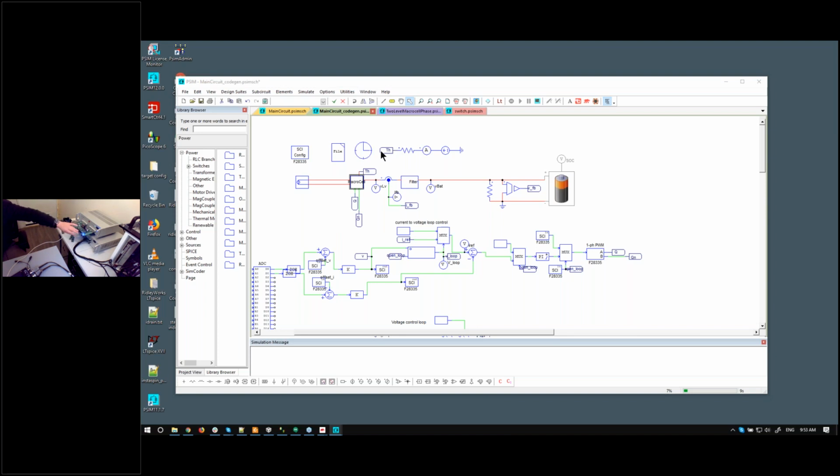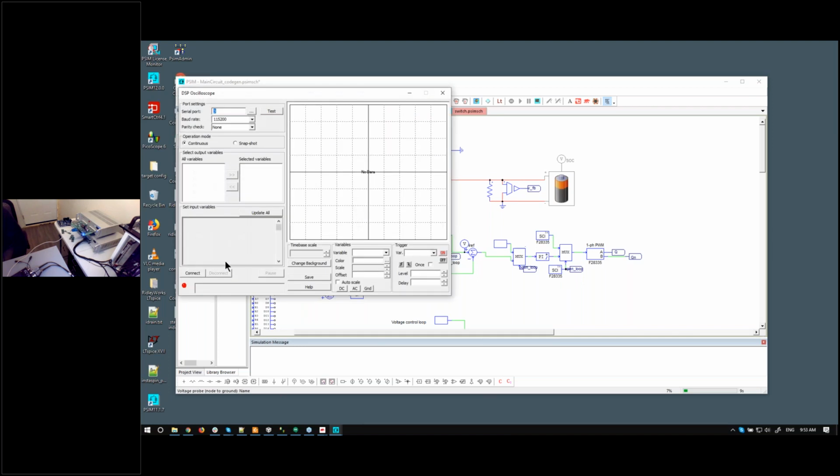So now over this cable here, I'm going to connect to the processor over serial communication. And what I'm going to be able to do is control, if you see in the schematic here, I've set up points where I can control things. So I'm going to be able to toggle this between open loop and closed loop, and I'm going to be able to monitor some waveforms as well. So let's just put this into open loop, and let's just define a straight 50% duty cycle.